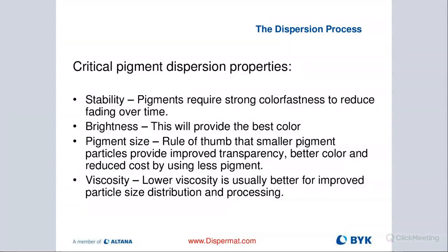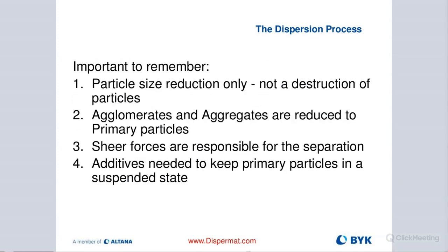So we want to shoot for about 2,000 to 5,000 centipoise. That doesn't mean we can't still mill when we are lower, but we may need a little bit more time. And if we go above 5,000, it's still fine, but it may be a little more challenging if we have some issues with flow with certain milling attachments.